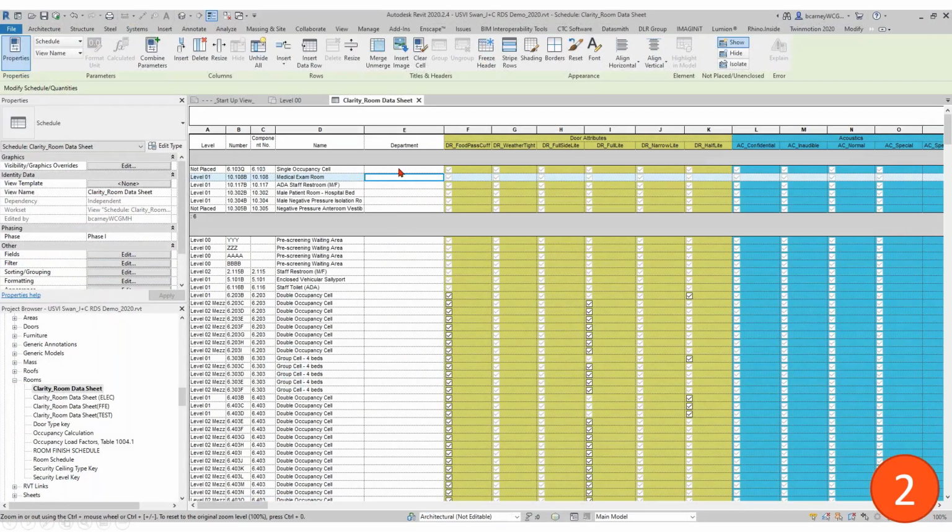So you skip that. We also primarily, I'd say, edit inside of Revit. So you can add all those parameters. These are added as rooms. You can checkbox and change. Something that I like to point out is to make some extra schedules and have them focused by the type of information you need, because I can't do that grouping and hiding here and I have to scan through.